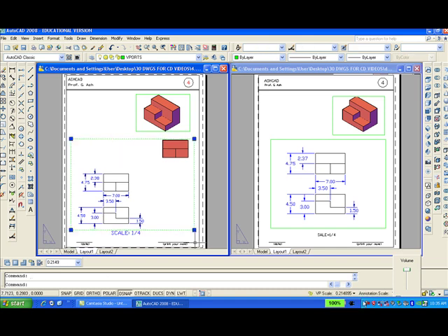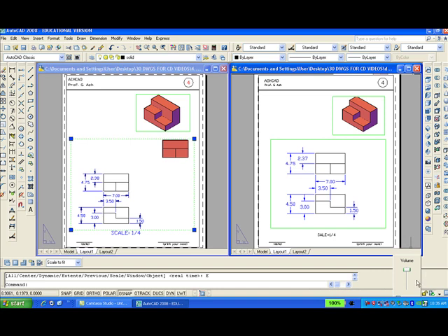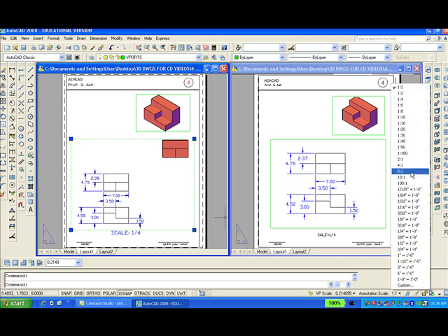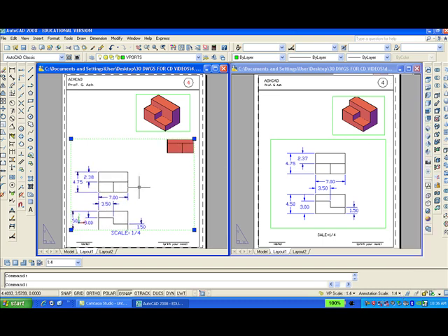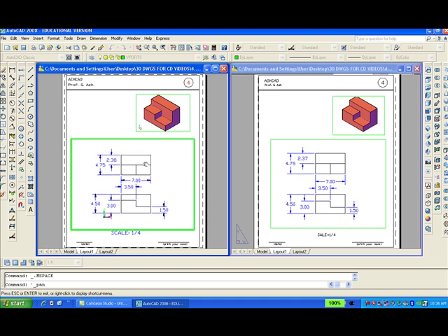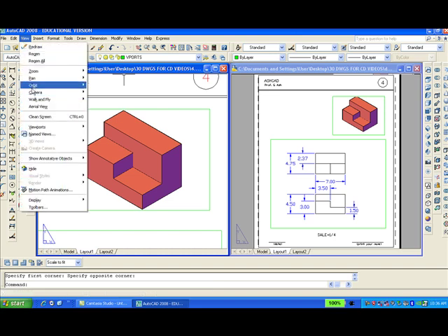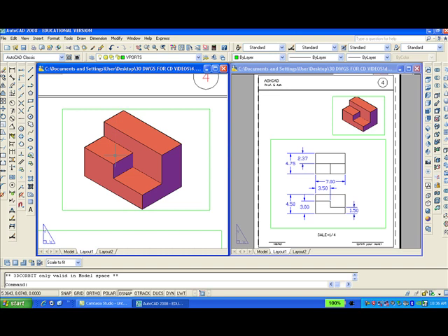Click on the large frame. That's in my way here. Okay. I want to go down to the annotative scale and make it 1/4. Double click inside, then pan. Looks okay. So double click outside, get into paper space. I'll zoom with the window to see what the solid looks like, and I'll view and orbit it in a continuous orbit. First, I have to double click inside to be able to do that.